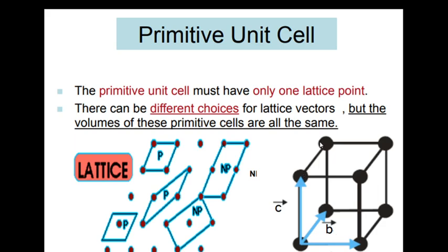So now you have 8 points, 4 on top and 4 on bottom, and since there are 3 axes A, B and C, the lattice parameters are parallel to the x, y and z axes, and therefore each atom is divided into 8 parts, where 7/8 portions are outside, but 1/8 portion will be inside the unit cell.